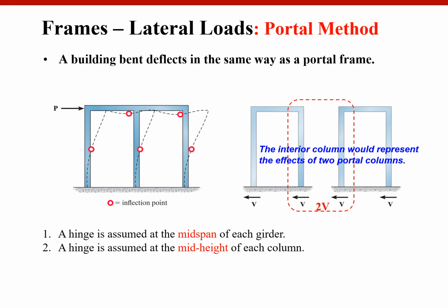And the third is that the interior column will carry double, because we are going to model this two-bay frame as two consecutive portal frames.